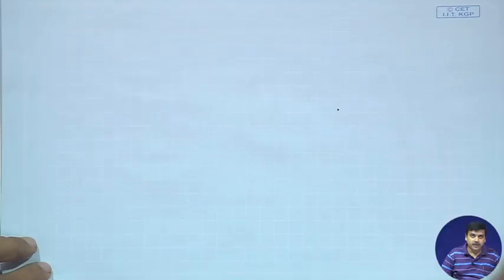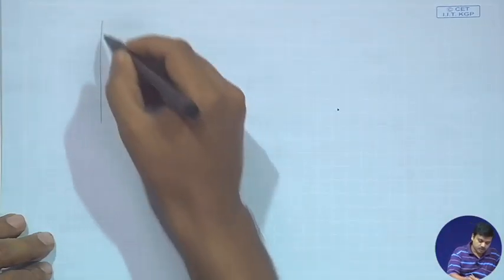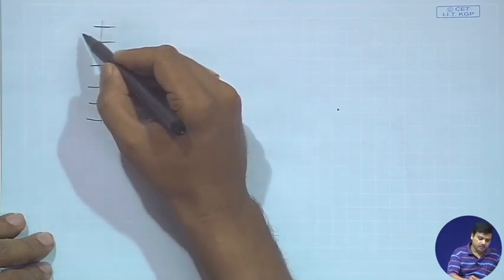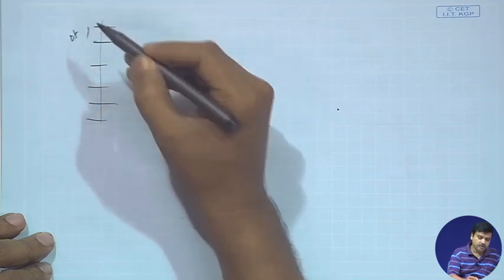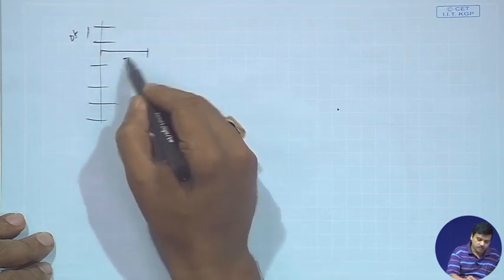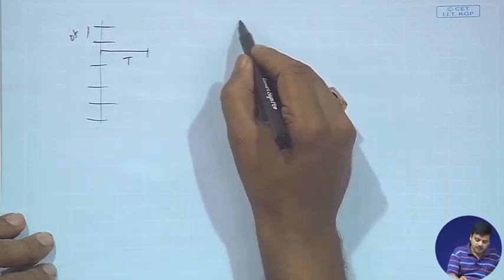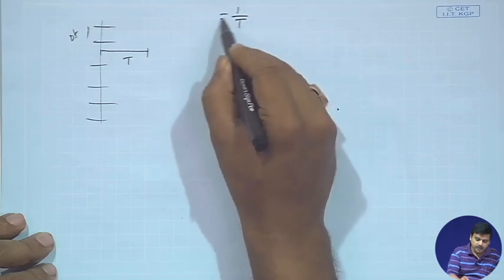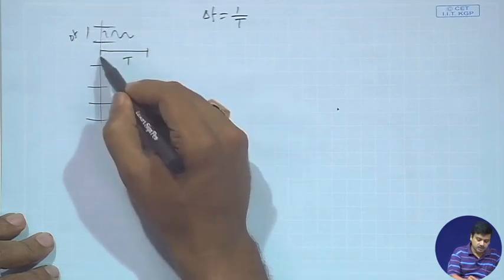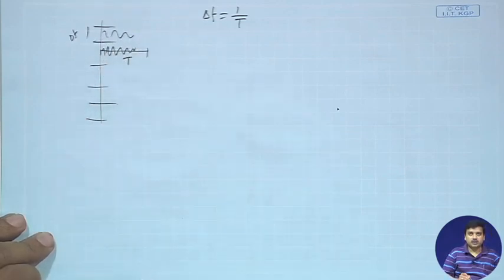Now, what we have studied for orthogonal signals, if you would recall, is that one way of creating such a signal was, if you have a bandwidth, you would divide it into orthogonal sections, where each sub bandwidth would be of size delta f, and if the symbol duration was of period T, then if you maintain delta f equal to 1 upon T, in that case these frequencies would be orthogonal to each other. That is what we have found.